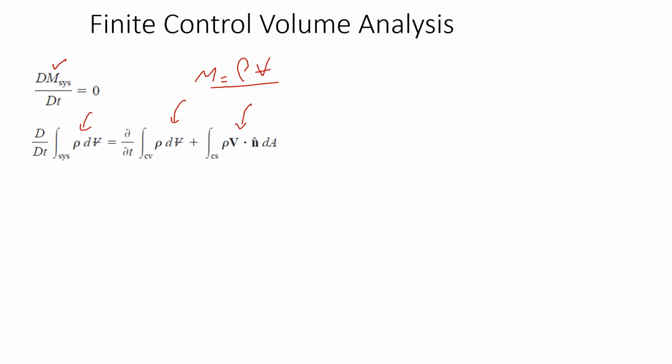So now this is our Reynolds transport theorem for conservation of mass principle. If we take the flow as steady, and by steady we mean that there is no change with respect to time whatsoever in the properties, then all the terms which represent the change in time become 0, and we are just left with this term. So this term was also turned into 0, and we were just left with the change at the control surfaces.